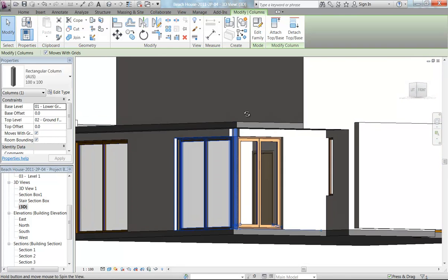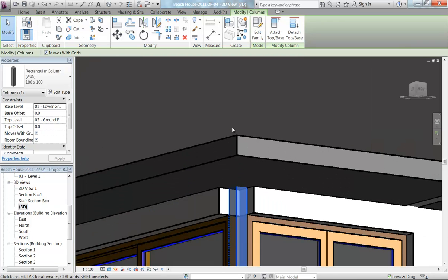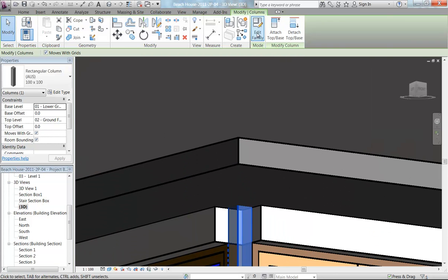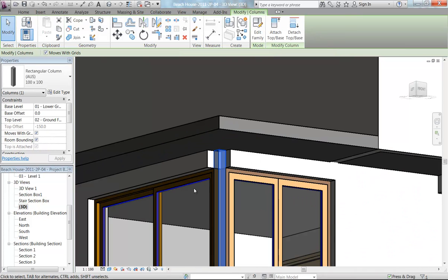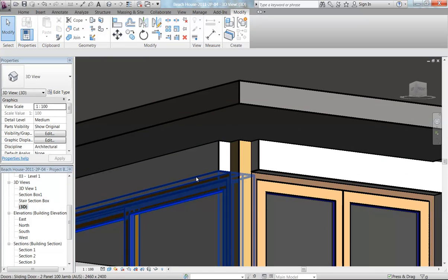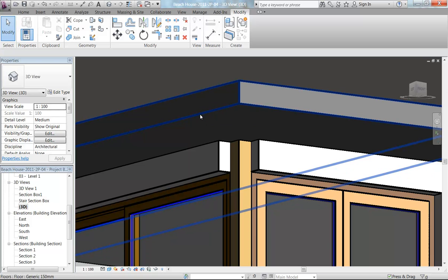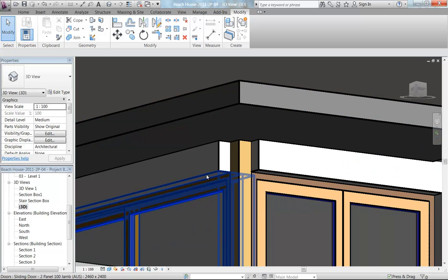So I'm just going to finish this video here, and you can see there's still an issue with this column. Now, I'm going to attach that to the floor, and then the walls here obviously don't look right. Now, I think what was actually done when this was built is that the windows and doors there were taken up full height to the underside of the floor. We may change the floor thickness anyway, so I'll leave it like that for now, and I'll have a think about it. In the next video I'll go through a way you can